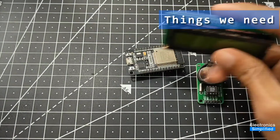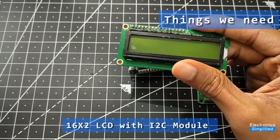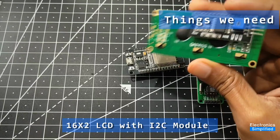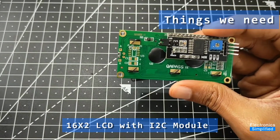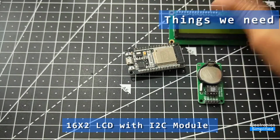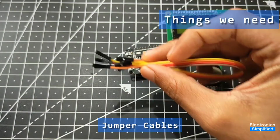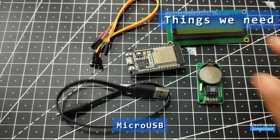And to show the real-time clock output, we'll be using a 16x2 LCD module along with the I2C mounted behind it. Now I'm using this so that I can simplify the connections, and we'll be needing a few female to female jumper cables, and a micro USB to upload the code.